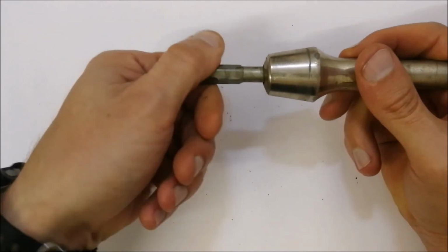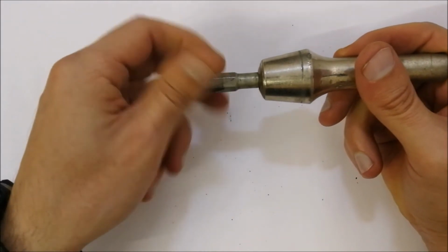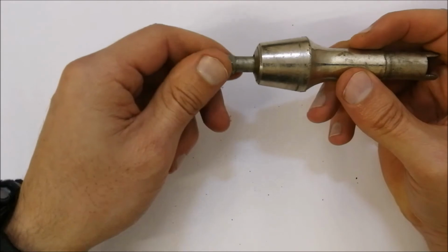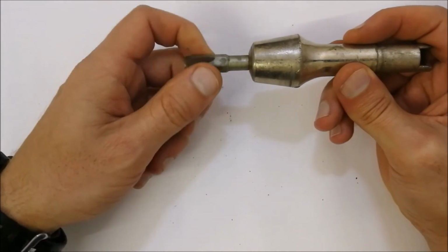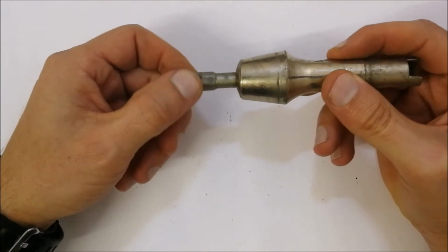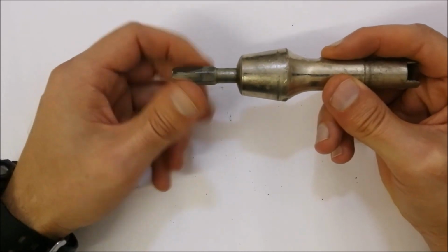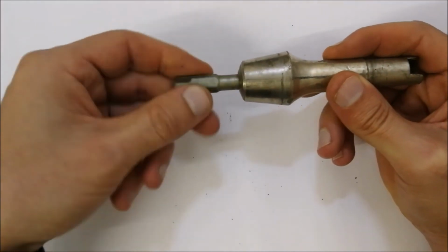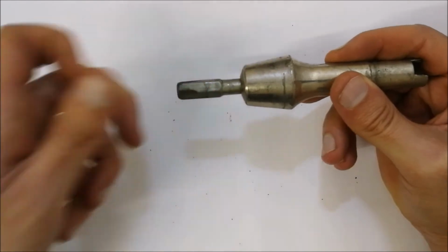If it was a bush, it would have been much more difficult, and there would be some friction involved. With this specific application where you've got the spindle, you want to minimize the friction, and therefore they would have a bearing inside of here to allow it to move more easily.